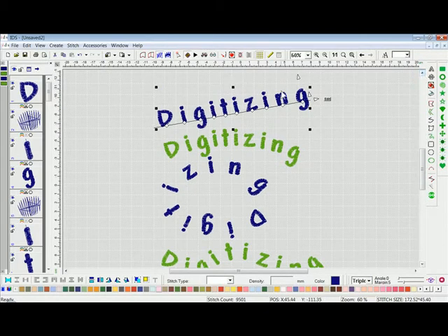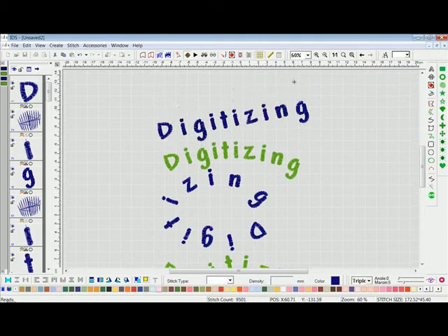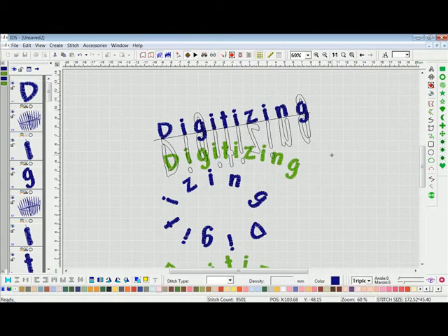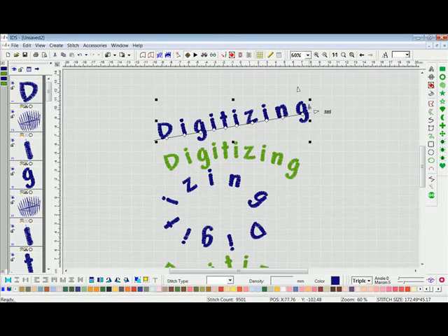word, we can see that we have those three arrows and the white diamonds. The arrow pointing up above the last letter will stretch our letters. Just left click, hold, and drag once it turns into that crosshair, or it will squish the letters or mirror our letters. The arrow pointing up next to the last letter will stair step our letters.